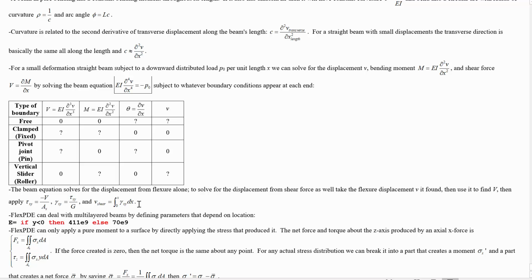Remember, we can have these shear deformations that really depend on the displacement of not just the x face in the y direction, but of the y face in the x direction. And you need both of those together, and we're ignoring one of them. So if you have a setup where that other one we're ignoring is non-zero due to the boundary conditions, if that's significant, then the shear deformation you're calculating using this is not going to be so accurate.